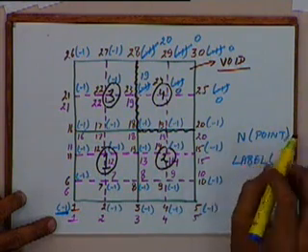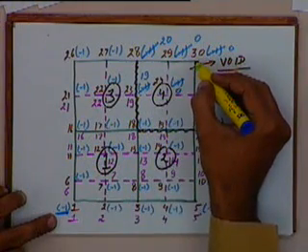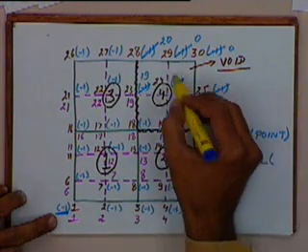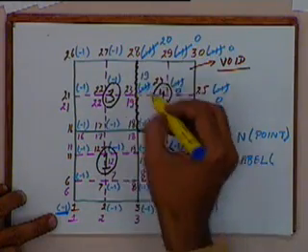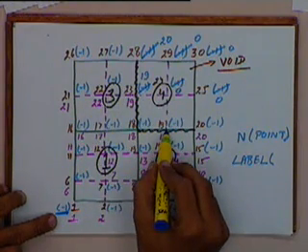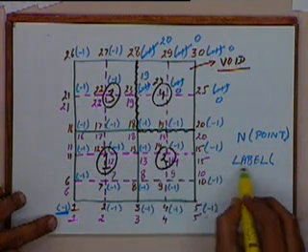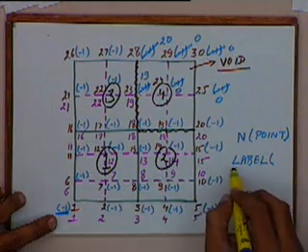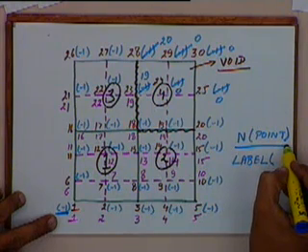What is the first array about? The first array is the label for every point. Initially it is -1 for all the points. For the void blocks, whichever points are inside the void block, I am putting them to 0. And for the edges which are being merged, I change the label of those points to the point number of the lower numbered point. So I get this array as label. Once I have this array, I use it to give a number to every point, and that is going to be my global node numbering in my final finite element mesh.